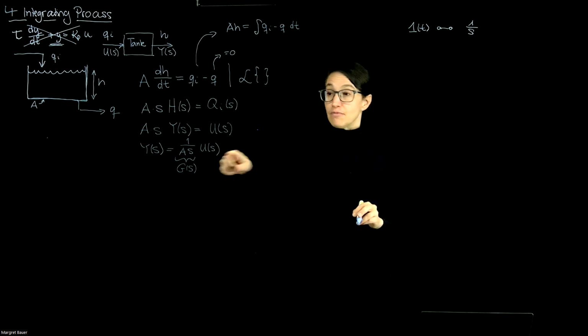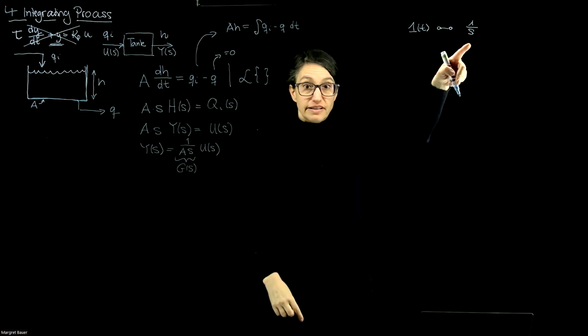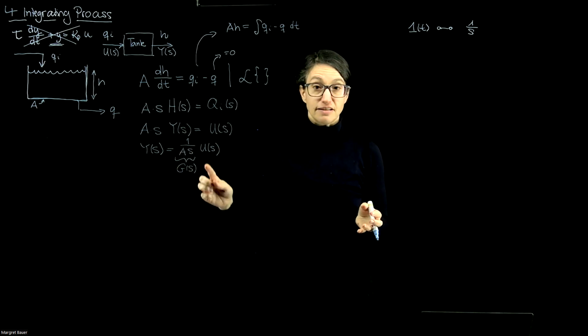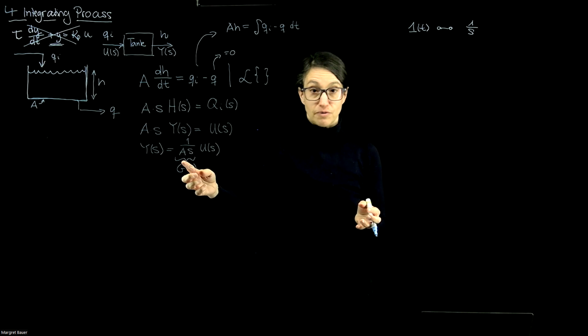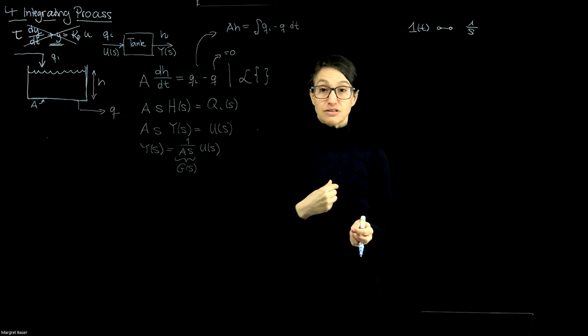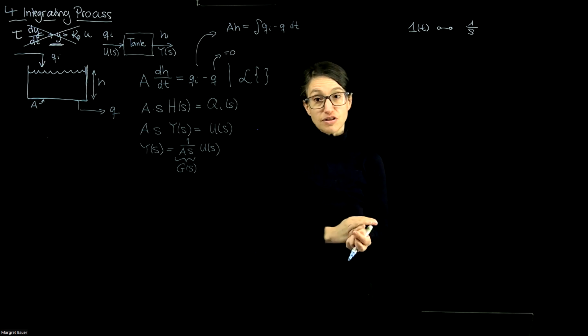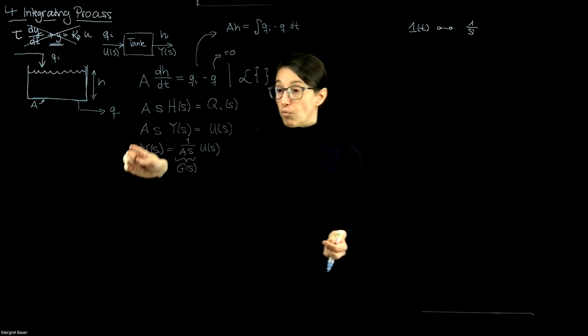And it has the same form. It's 1 over s, and this is 1 over s, but we're not doing the inverse Laplace transform of that signal on its own, of that system on its own. We can do the inverse Laplace transform of, for example, the step response. So if you wanted to do the inverse Laplace transform for our y of t.